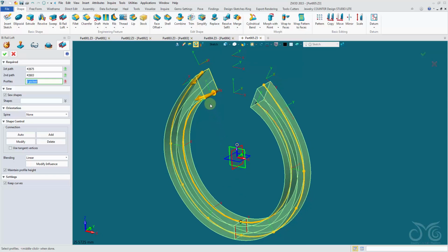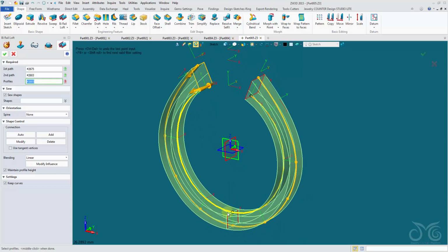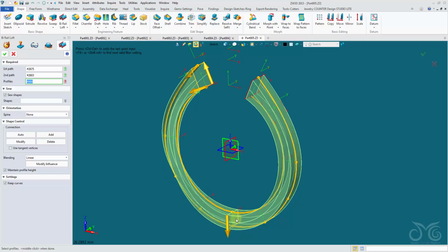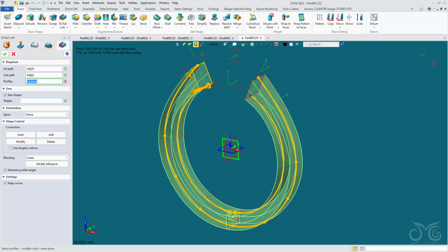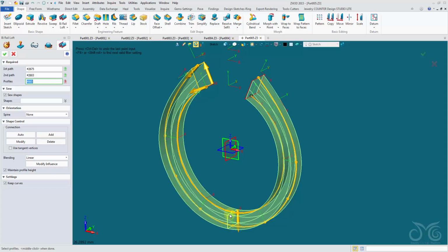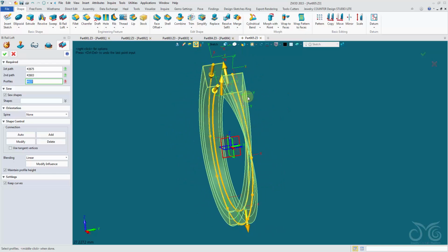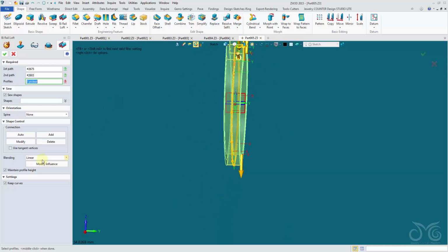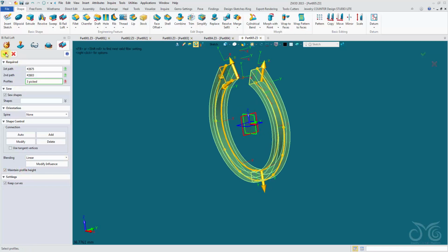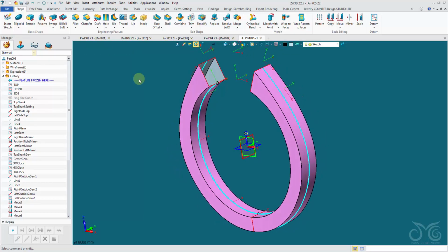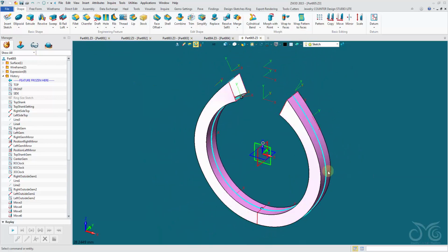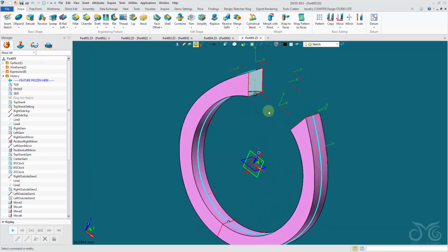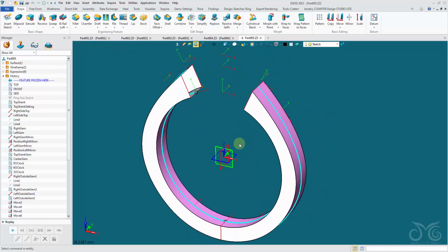Okay, you see here how we tried to pick on the same bottom part of our sketch, but it allows us to only pick on the sides. Just make sure that the arrows match up. Again, obviously you will see in the preview if your bi-rail loft is not right. Okay, so if you have the open shank, your bi-rail loft may not come in with the end caps. Okay, in which case we can add them in ourselves, it's not a problem.